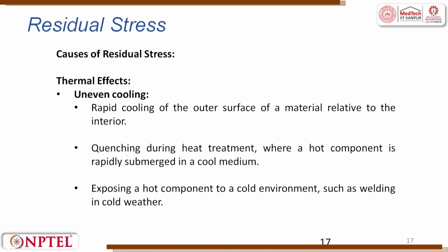Quenching is you try to heat it and then you try to cool it immediately. You could have seen in an ironsmith, when he wants to deform an iron, he keeps on heating it, and then he tries to deform it and then quench it. So, quenching during heat treatment, where a hot component is rapidly submerged in a cool medium. Another thermal effect is exposing a hot component to a cold environment, such as welding in cold weather. All these events which happen during manufacturing processes, where thermal effects are dominating, lead to residual stress.